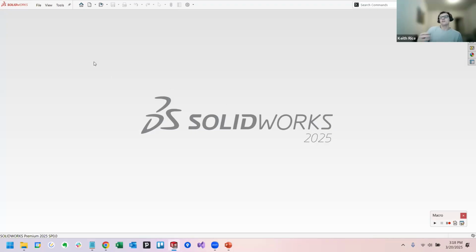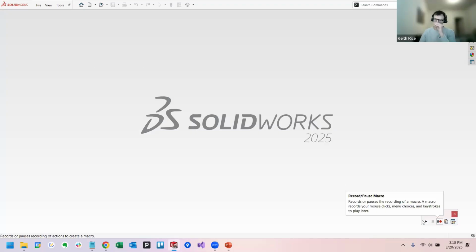Okay, so what we're going to do next is take a look at the macro recorder. And I might as well ask that. Is anybody, no, I guess nobody's even used the macro recorder. I don't need to ask that again. The absolute simplest way to use the SolidWorks API is through the macro recorder. So if you're not sure where to start and you just want to say that you did something API related, the macro recorder. Again, it's accessible through the macro toolbar.